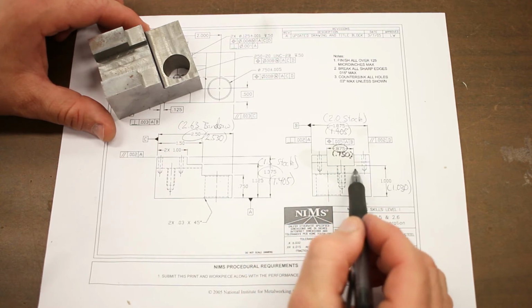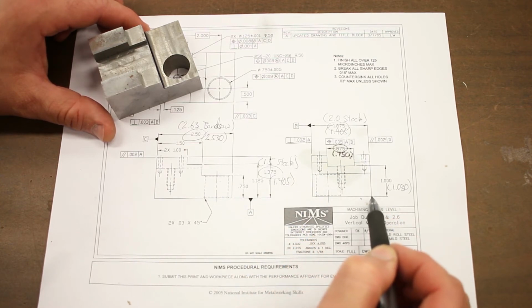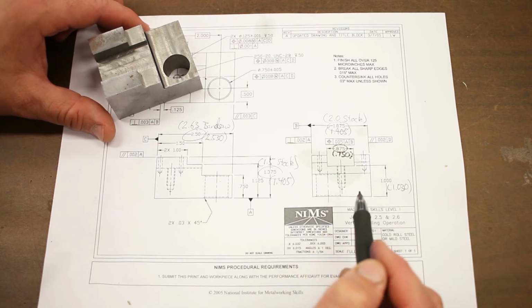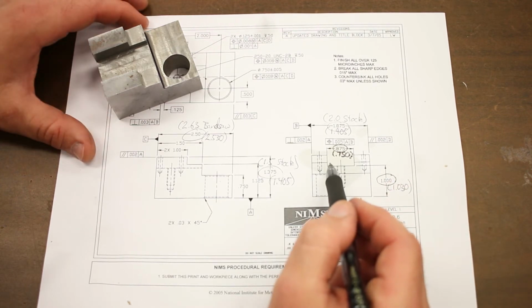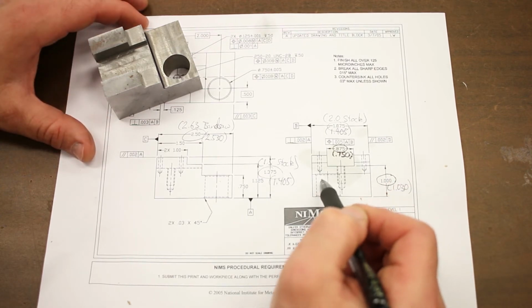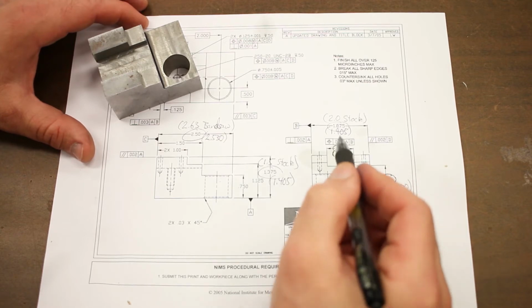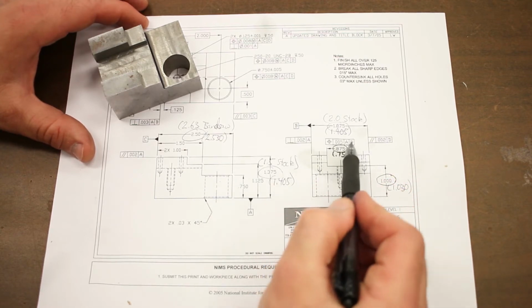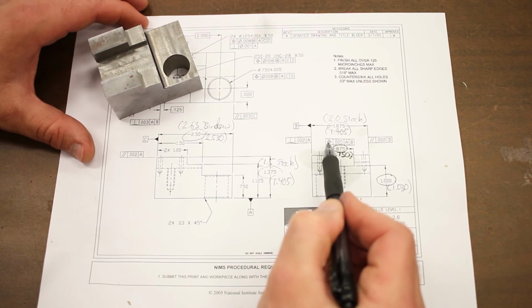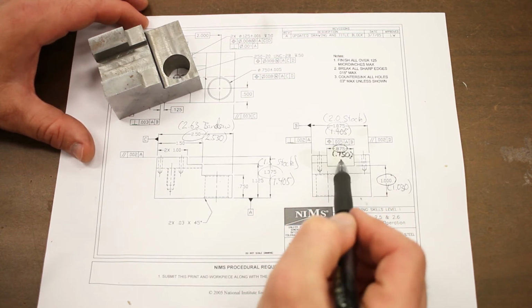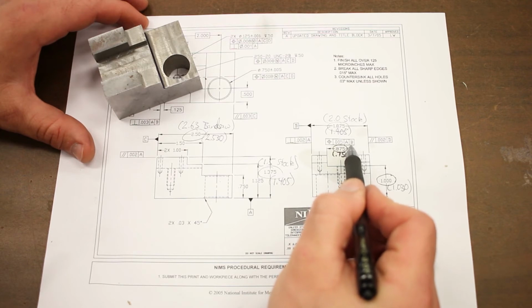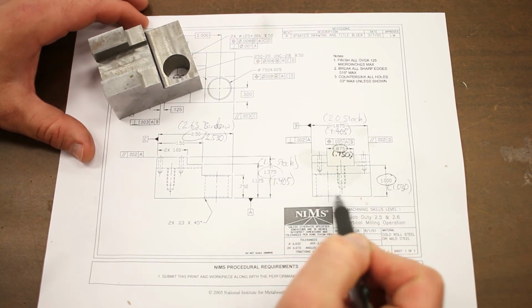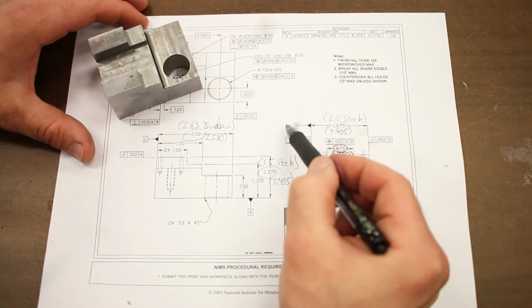Actually, the depth is not given to us. The distance from datum feature A to the bottom of the slot is given to us, and that's 1 inch. As well as having a size, of course, the slot also has a position, and the positional tolerance is provided here by this tolerance of position control. So this is a GD&T control which applies to the slot. The tolerance is 5 thousandths relative to datums A and B. Well, datum A is the bottom of the part, and datum B is this datum right here.